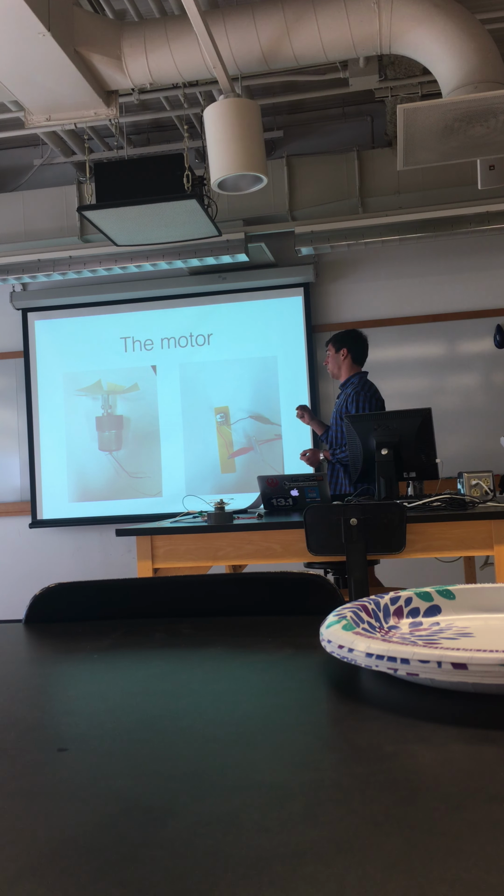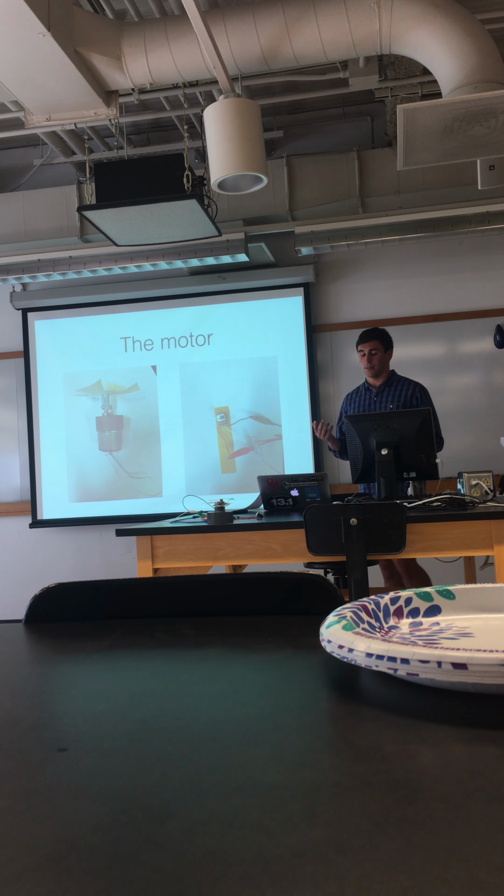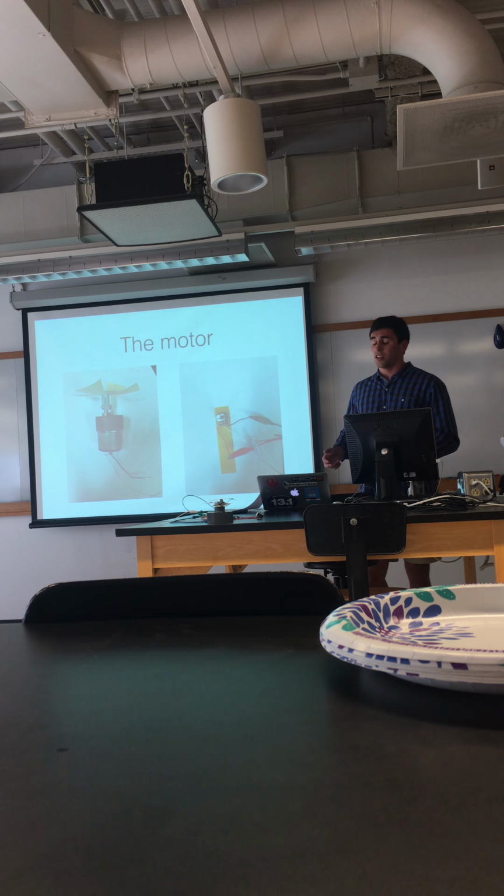By fitting that spacer nut onto the axle and drilling a hole in the spacer nut, I was able to take just an M3 screw, which is just a measurement little screw, and put it through both the spacer nut and the hole in the motor axle, keeping it steady. And then the fan is just attached to the spacer nut with super glue. Sorry.